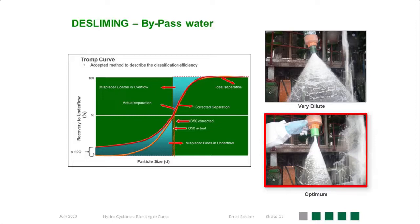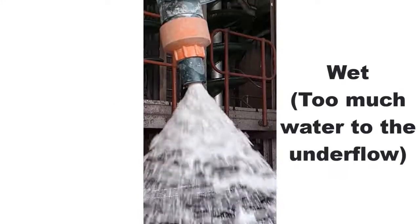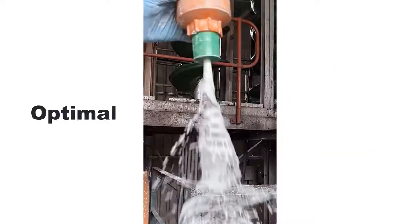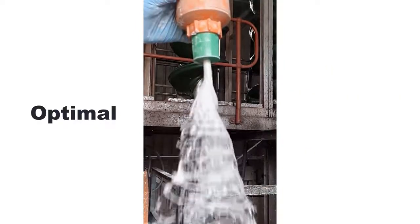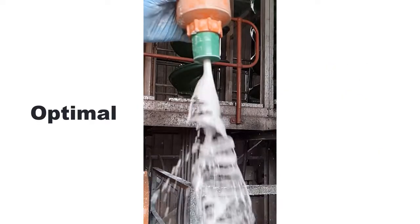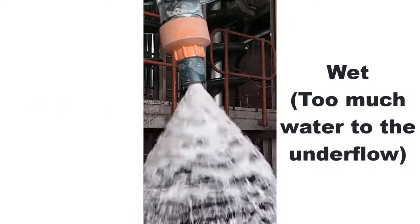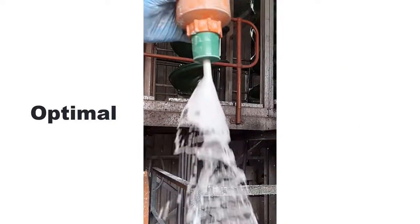The picture on the bottom right hand side of this presentation shows a more optimum underflow discharge. To illustrate that via actual practice, this video shows the difference between a wet underflow and an optimal underflow from a hydrocyclone. It's therefore important that you must be able to see the underflow discharge from a hydrocyclone. If you can't see it, then you don't know how the unit is performing.